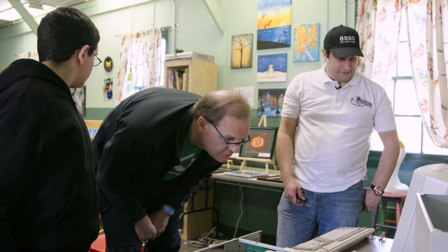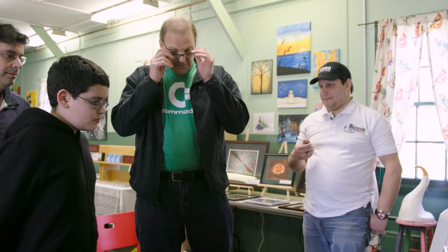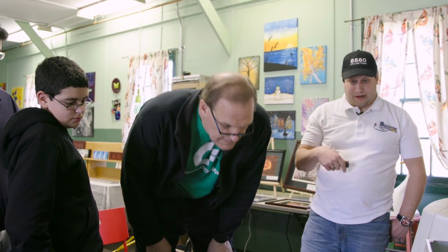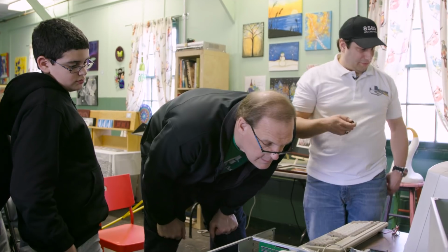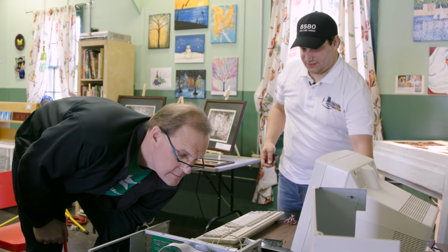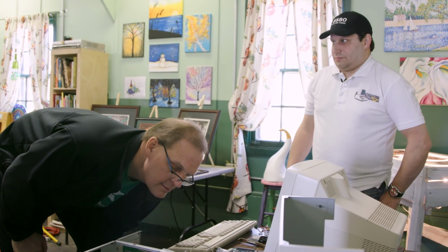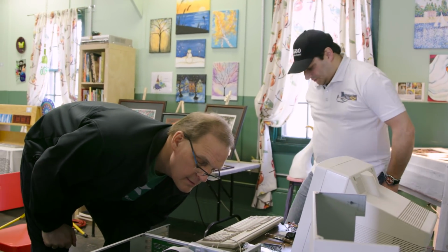I mean, you should get a color for bad chip RAM. You should get a green screen, unless the green screen comes after the purple screen. But it's not the point of testing chip RAM to be getting to the purple. Otherwise, right now, we'd be showing a green. So whatever the problem is, unfortunately, if I remember from the list, chip is pretty far in the process. So it still leaves a lot of potential problems along the way.